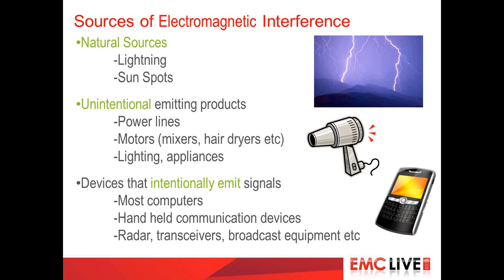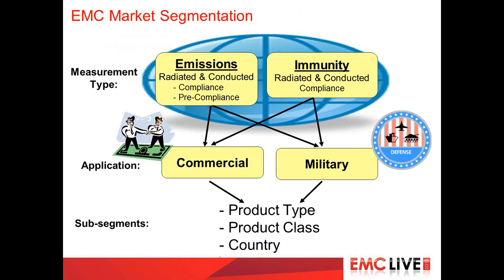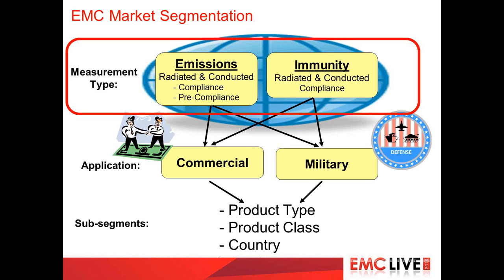But the whole idea of EMC testing is that we want all these devices to be able to be in the same environment and to be able to operate without interfering with each other. Looking at EMC as a whole, you can look at it as a type of measurements out there. And we have, in general, emissions and immunity testing. We'll take a look at that in just a second. But you also have the application. Both of these measurements are applicable to commercial and mil testing.